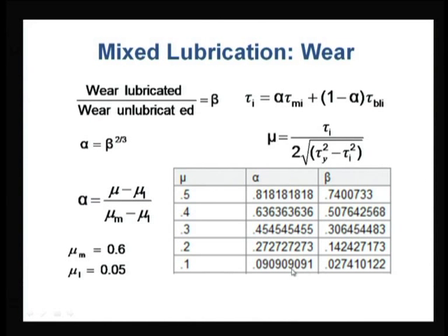If you see the definition of lubricant in a common English dictionary, it says a substance which reduces the friction, but here we can say that it is a substance which reduces the wear predominantly, and friction also. So, it reduces the friction as well as wear. More emphasis is given on the wear. You can see the comparison here, the 3% and 10%. Reduction is by 97%, while in this case reduction is by 90%.